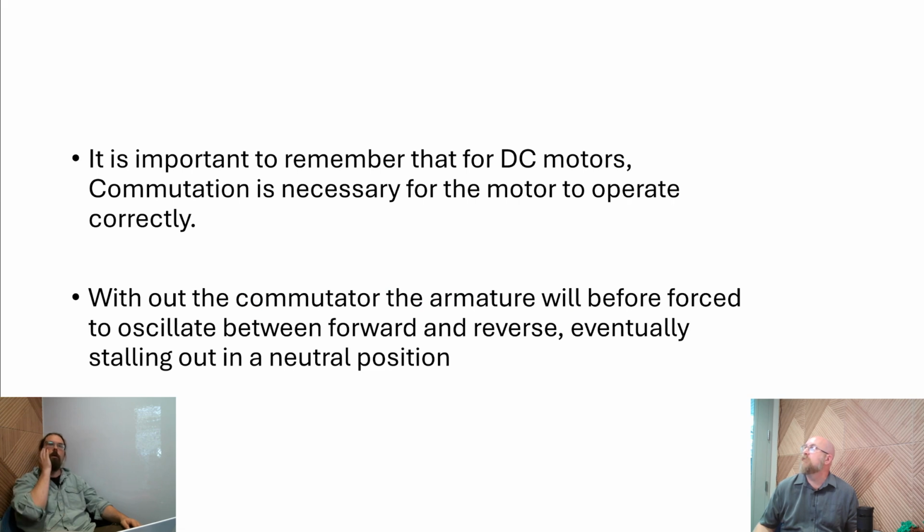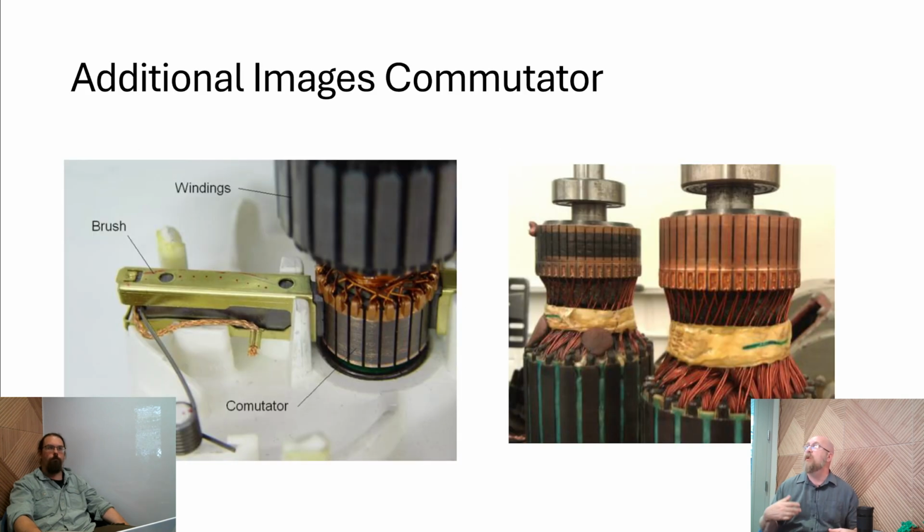The main thing for DC motors is this concept of commutation and the commutator, and how it relates to how we're doing power input. Remember when I was talking about different polarities repulsing or attracting? If we just had a motor hooked to DC with current going in one direction, nothing would change, so it would lock itself in position and not rotate. So we need to do something called commutation in order to alternate the current inside there.